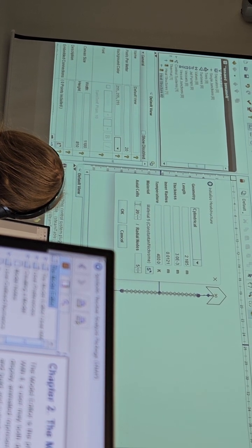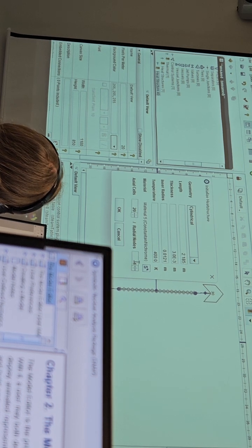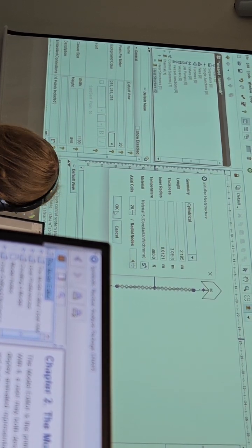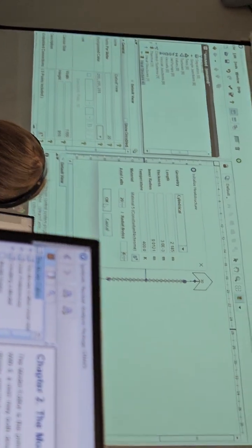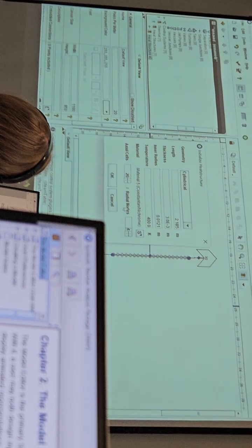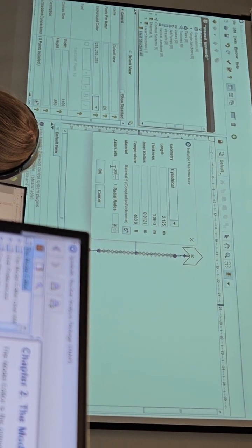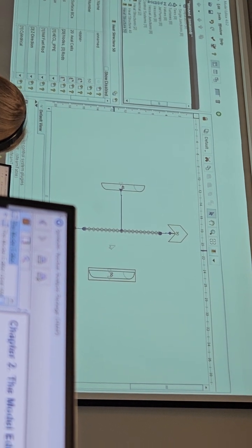Axial cells is 20, radial nodes, we can also leave it as 5 or even reduce it to 4 or 3. It will make calculation a little bit faster. These heat structures usually take a lot of computational power, and the more radial nodes, the more axial cells. Also you can make a multiplication of the heat structures.